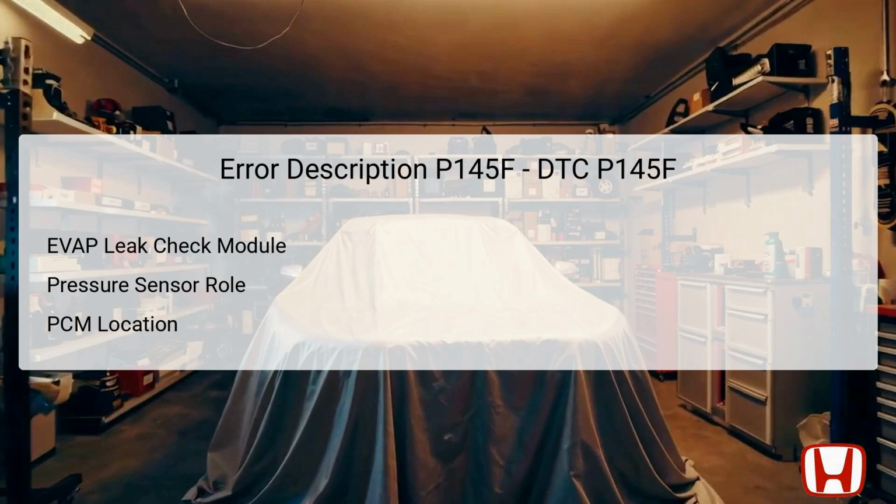The Evaporative Emission Control System in the Honda CR-V includes a critical component known as the EVAP Leak Check Module, ELCM. This module is responsible for monitoring the pressure of the fuel vapor system to ensure that no leaks are present. The pressure sensor within the ELCM plays a vital role by measuring the vapor pressure in the system and relaying that information back to the PCM. Located near the fuel tank, the ELCM is integral to optimizing vehicle emissions and achieving compliance with environmental regulations.